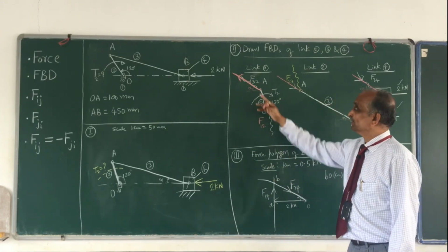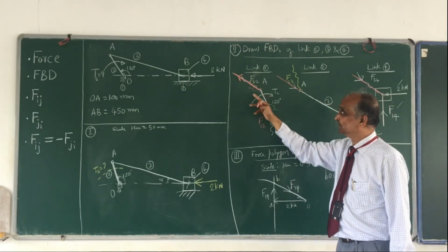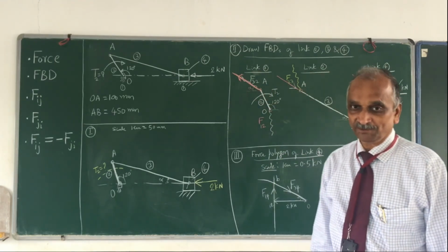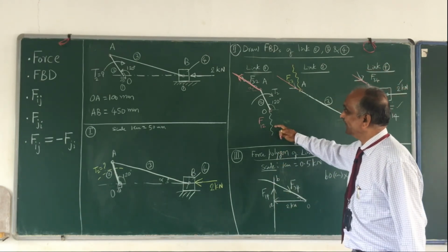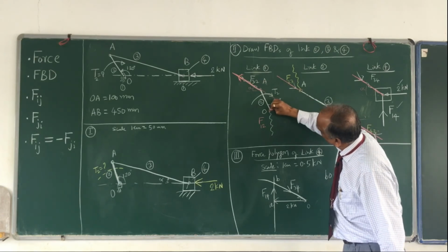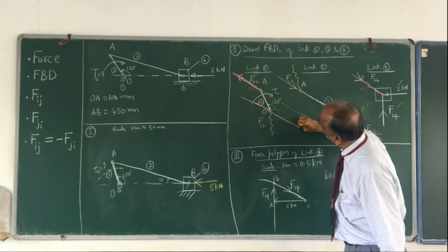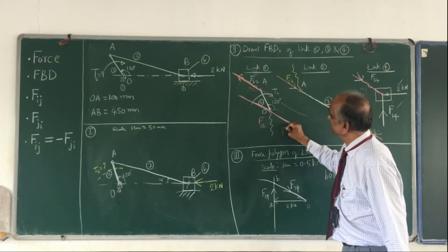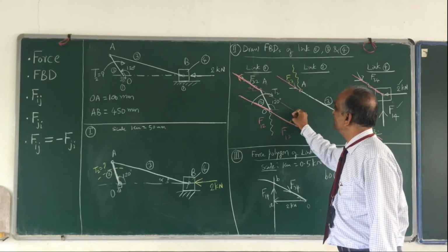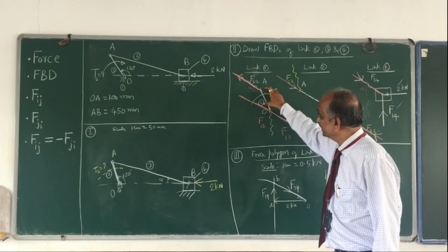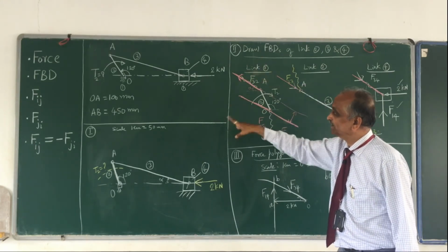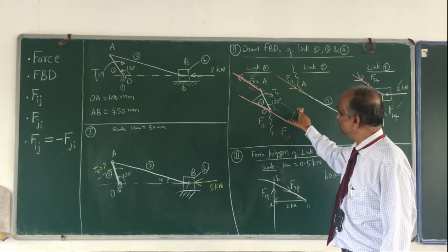Okay? Now, I am making use of the earlier discussion, two force and torque. The two forces must be parallel to each other. So therefore, F12 is also, extend this, parallel to it. This is what is your F12. This is F12. And find out what is the perpendicular distance between them. You have drawn it graphically, you measure it. This measure multiplied by the scale. 1 centimeter is equal to 50 mm. This is so many centimeters.